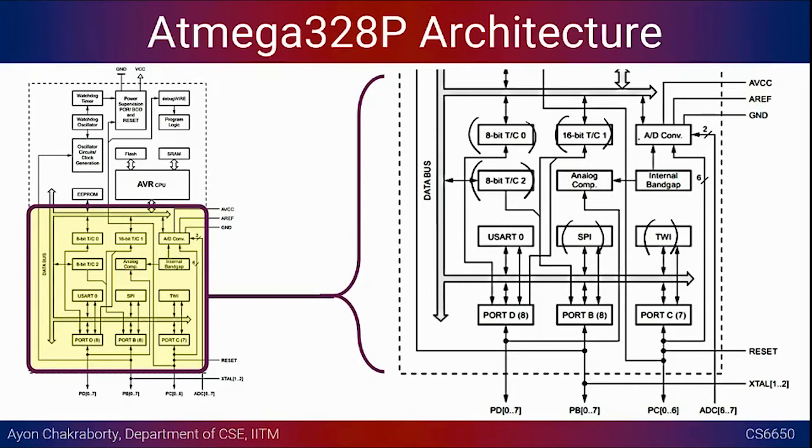Okay. And then this analog to digital converter is always there, with some of these inputs that A to D converters take. There's a reference voltage, ground, and so on. And this is pretty much it, right? So all these things will help you with sensor interfacing. Okay, and this is the A to D part if it is an analog sensor. If it is a digital sensor, I would say this is for digital sensor interfacing, because all these are digital buses, right?